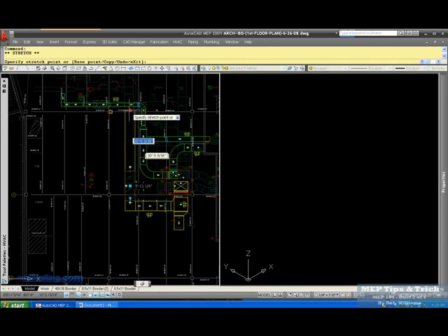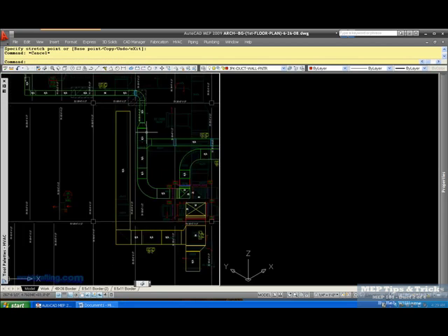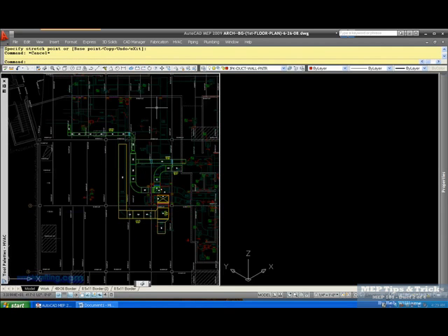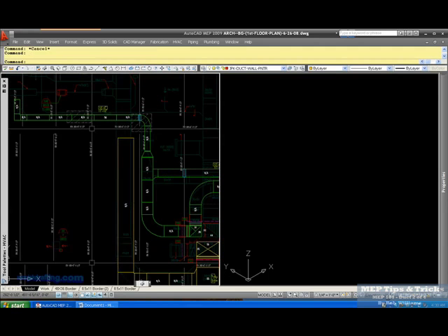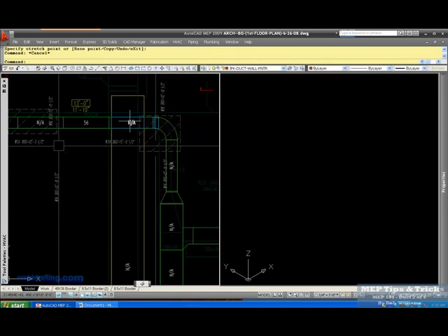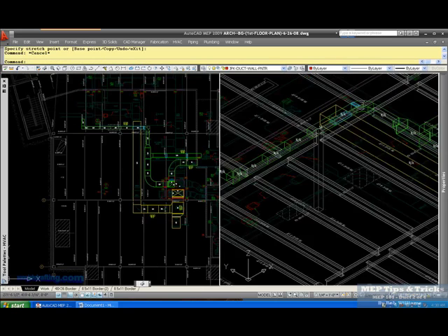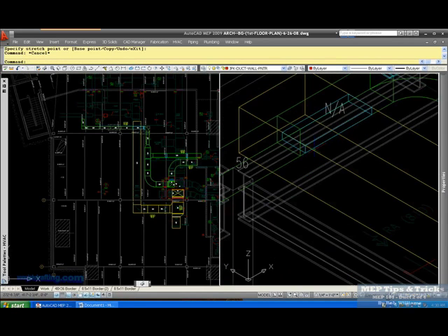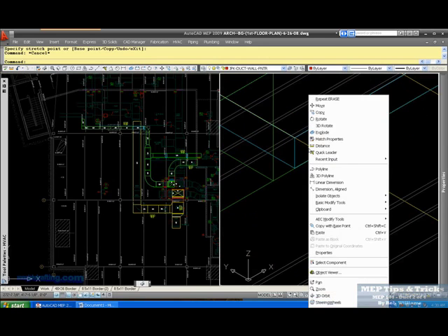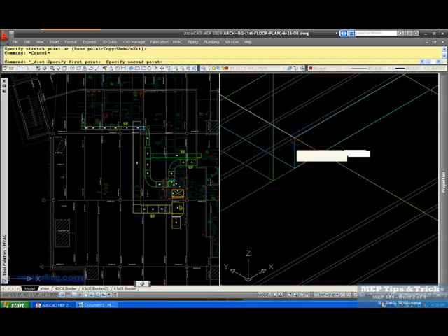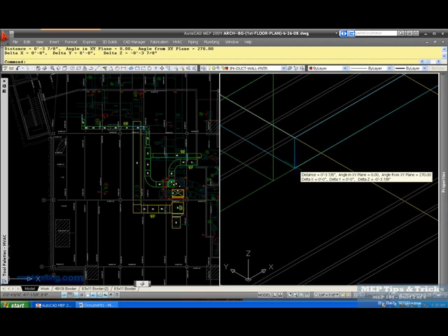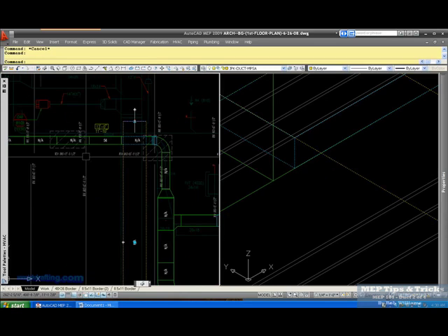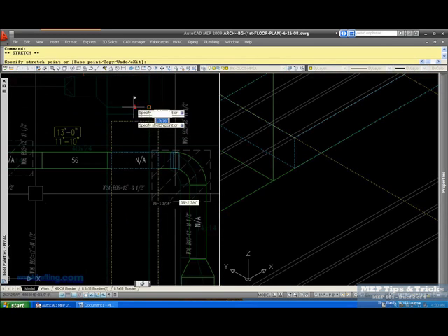So in other words, now we're going to draw this duct down to here, and let's go ahead and offset underneath this one. So we're going to draw down here. We're crashing, right? So you come in here, you're going to see you're crashing. You can test this, and we're 3 7/8. So you want to be down 4, 7, 9 inches, so that you can insulate. Well, it's an exhaust duct. You wouldn't have to go down 9, so we want to go down 7.